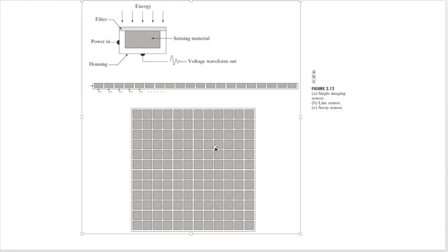That's why a lot of this looking for different semiconductors and everything is a materials process, because you're trying to find ones that are going to absorb photons in the energy range you want, or emit them in the energy range you want. So it's going to get struck, it's going to emit an electron, that electron will flow. So every photon that hits creates a charge carrier. You get more photons in the right band, what happens? You get a really good current. So I reverse bias it, it prevents there from being any stray currents happening, and then anything that gets struck, right, by a photon is going to generate current, and I can measure that current.